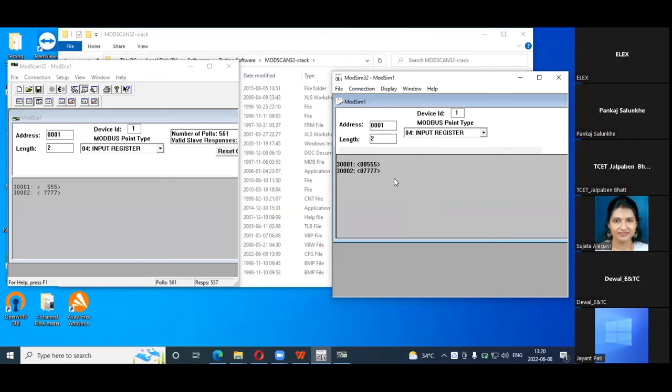So here we can't write anything in the RTD. We just read that RTD temperature data. So the manufacturer used it as an input register. The input register has the property that it is read-only. So the data is written in that input register.